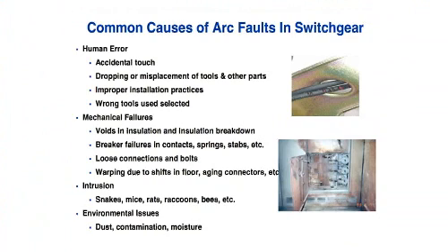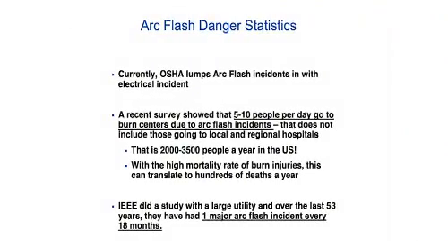And then lastly, you have environmental. This is when coal dust and other types of environmental dust particles in the air will land on buses and contaminate them. Near the seashore, obviously you have salt in the air. All of those have a debilitating effect on the switchgear itself. Okay, so taken as a total, you can see there's a lot of things that can and unfortunately do go wrong with metal clad gear.